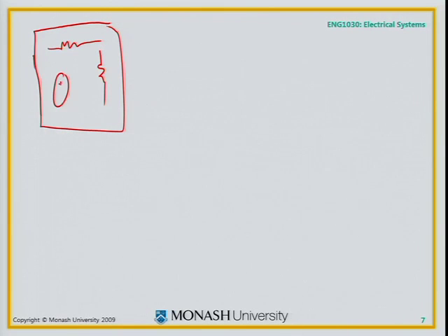Terrific. What if I put voltage sources and current sources in that box now? My circuit has more elements in there. It might have some resistors, but it also has voltage sources and maybe even some current sources wired up. I want to work out what's inside the box. Well, there's only so much I can do. I can again probe, putting resistors or voltage sources or current sources there, producing a certain voltage and a certain current, exactly the same way.